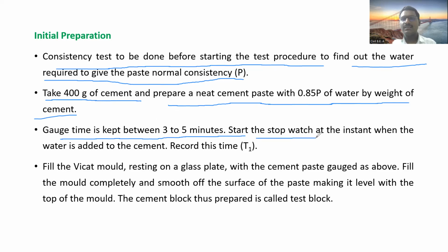Then start the stopwatch at the instant when the water is added to the cement and record the time. It means when we started adding water, at that time 0, within 3 to 5 minutes, whatever time we take to make the paste, that time is recorded as T1.